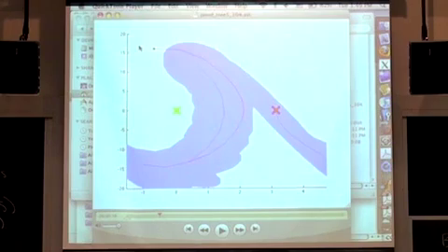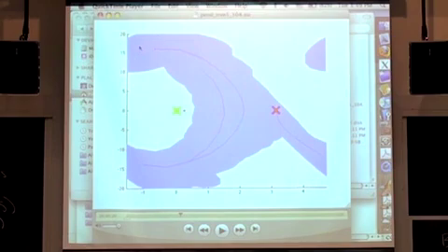Connect that back. Now this one, my dynamic distance metric, which was that LQR distance metric, connected and said this was the closest point. Looks a little surprising, but maybe the torque limit said that one couldn't get there, or maybe my distance metric just wasn't perfect. But that's reasonable. It tries to go from here, add a little bit more torque, and drive out, and I stabilize that with a funnel. Yeah?